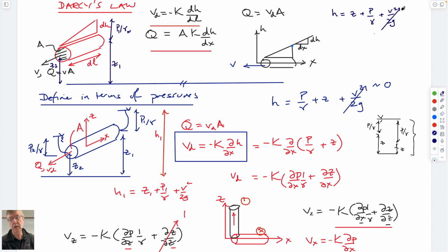And the changes in velocity, and typically the absolute velocities, are small enough that we typically get away from that. Remember that this term represents inertia, what energy, what force it takes to accelerate a fluid. They're not accelerating very much because they're going at very slow velocities. And most of the energy is used up not in accelerating the fluid, but by viscous drag. This is the friction factor, essentially. Hydraulic conductivity is essentially a friction factor.